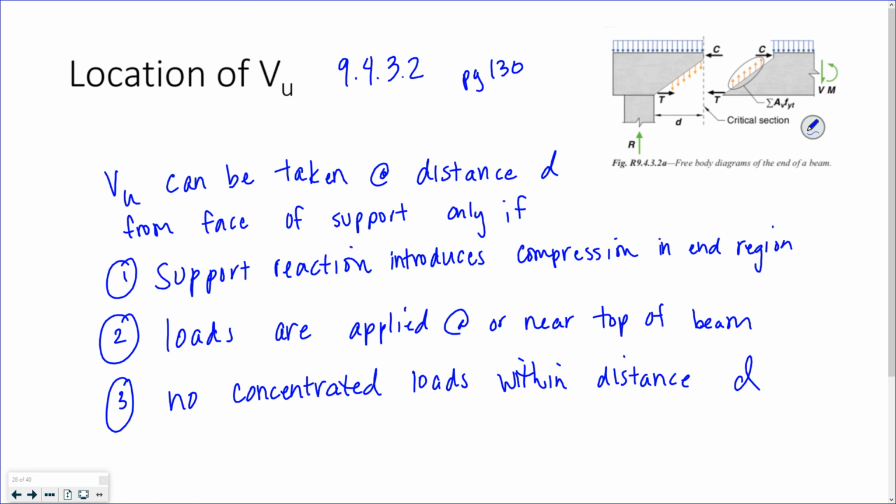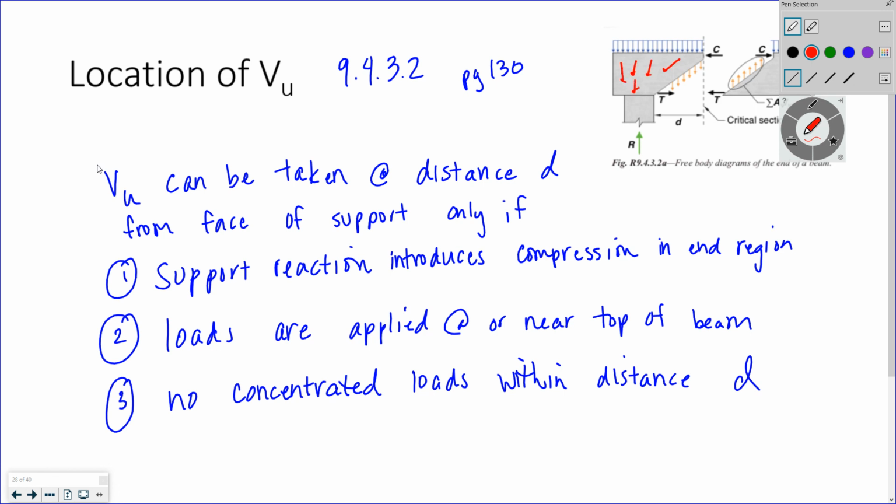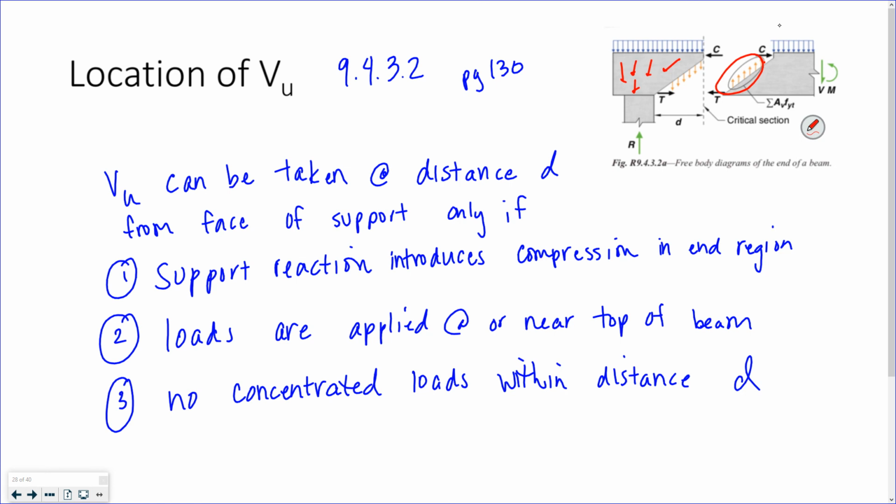At the top, right? If there was a concentrated force right there, that might not actually be too bad, but if it was like right there, then you wouldn't be able to do this. And you can see the load is up at the top. All that force is just putting this in compression. And that's your critical section, where you have your Av over s times d times fyt. That's your shear contribution, and then your Vc as well.